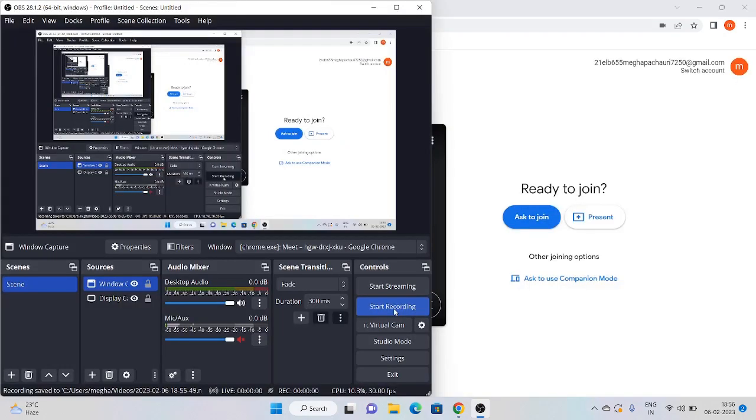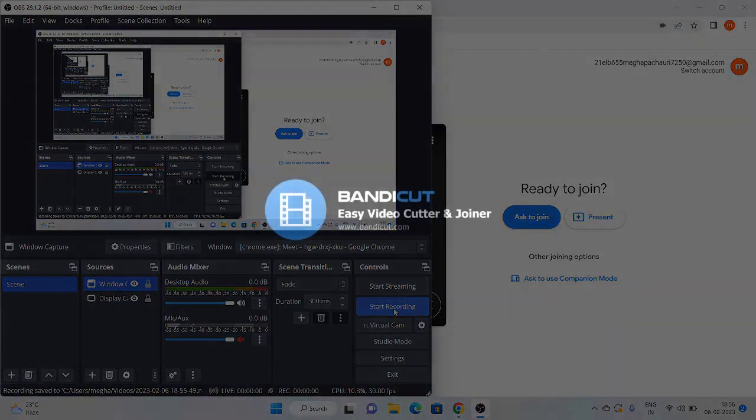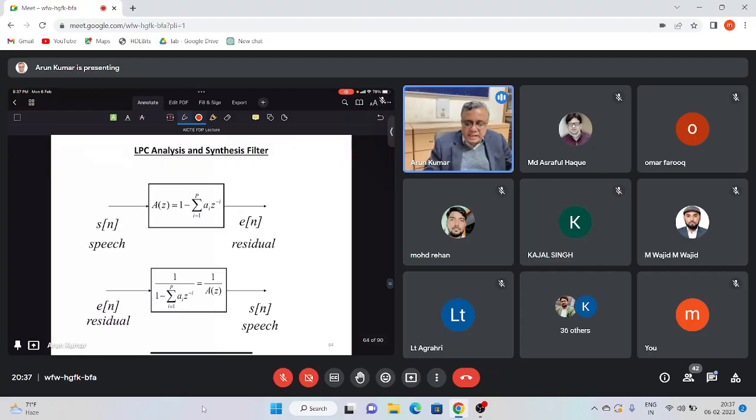So now we can estimate the vocal tract model from the recorded speech signal. And the output of the inverse of the filter A(z) is the residual signal, or vice versa. We can take the residual signal, which ideally is the input to the vocal tract, and the output of that is the speech signal. So 1 over A(z) models the vocal tract resonances.